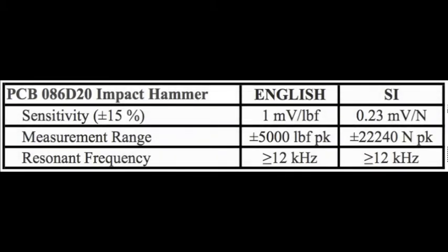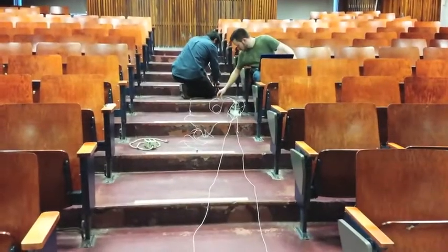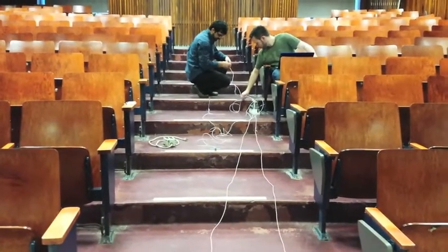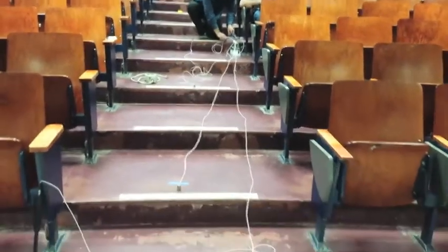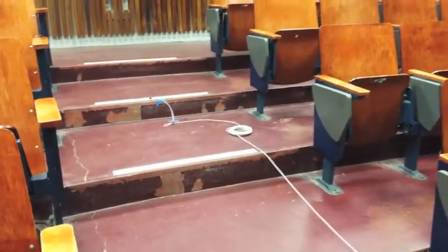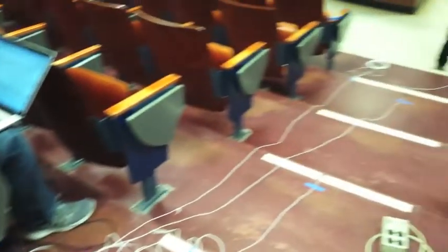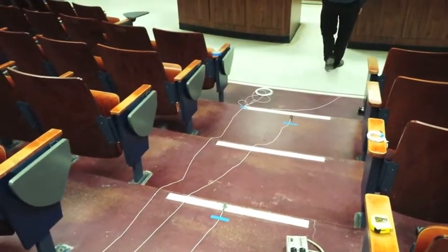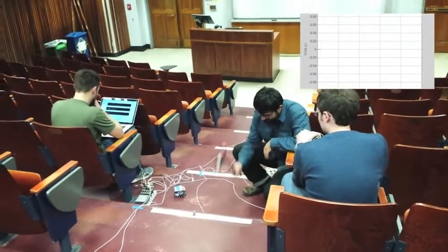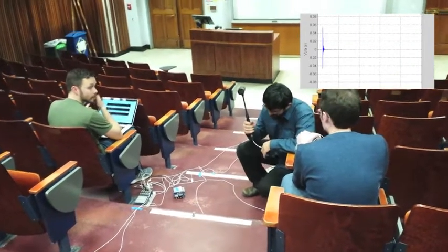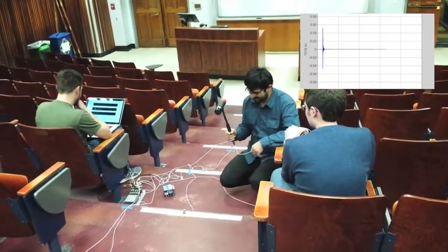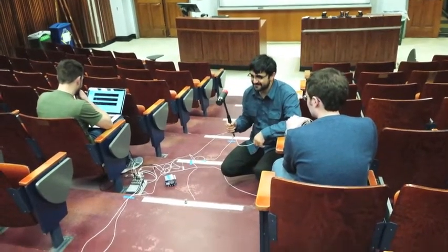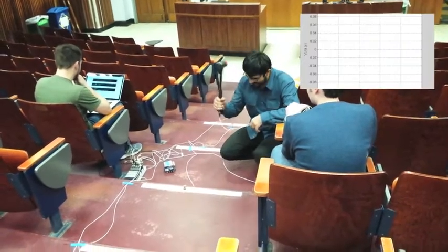We employed a National Instruments compact DAQ with sampling set to 2048 Hz and used an anti-aliasing filter. At each location, the impact hammer was struck 10 times. The time histories of the impact hammer and accelerometers were saved for post-processing. The time records were used to create multiple averages for spectral processing.